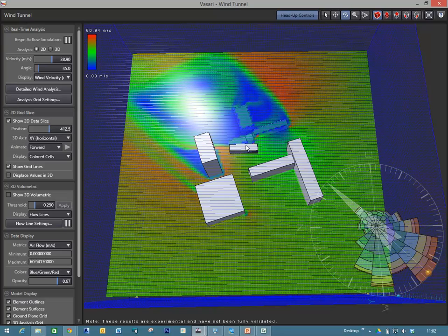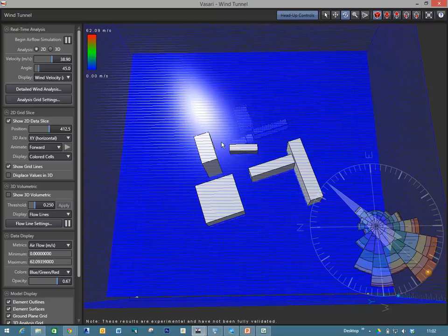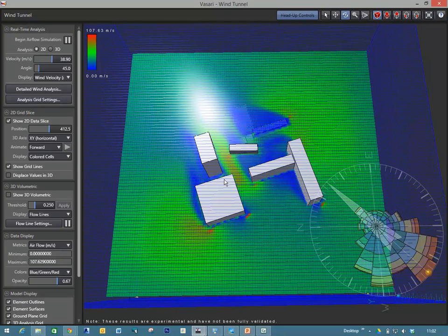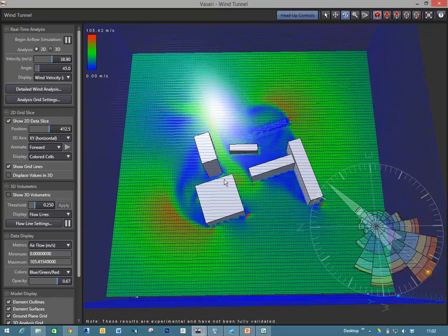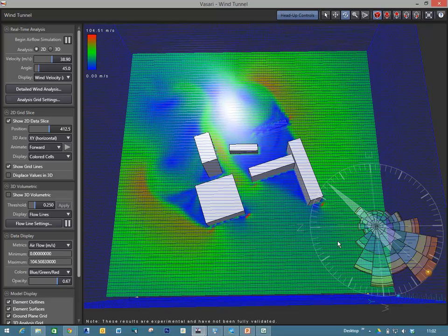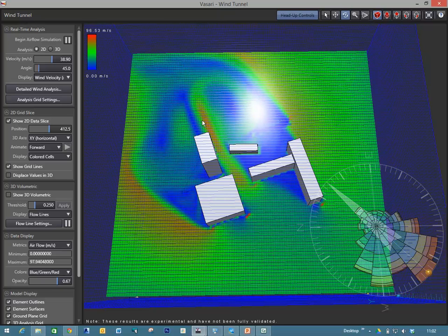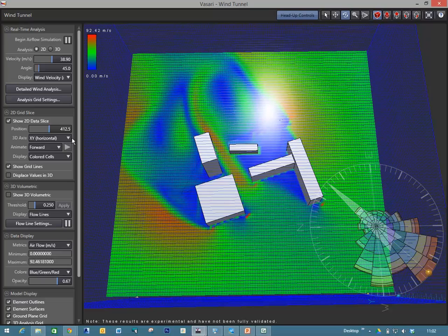Are you getting a particular sort of acceleration of wind, causing problems at the pedestrian level? We're all familiar with what happens at the bottom of this arch tower on a windy day, where the wind gets accelerated. So the kind of thing you might be looking for, if we're looking at the wind distribution here, is these accelerated zones, because they give us a potential warning that we're getting very high wind levels.